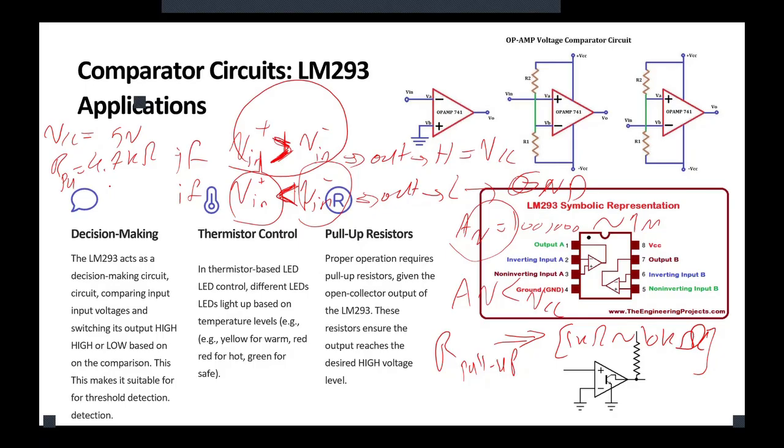Now the current through the pull-up becomes 1.1 milliamp. That is perfectly fine. It's low enough to avoid heat, but it's fast enough to basically switch the logic. Now let's actually build that.